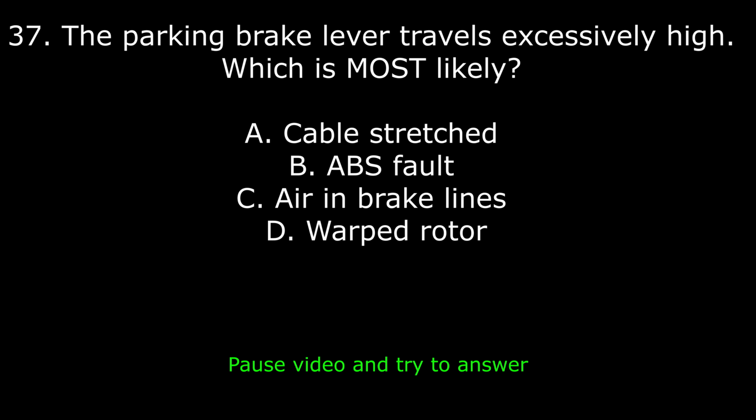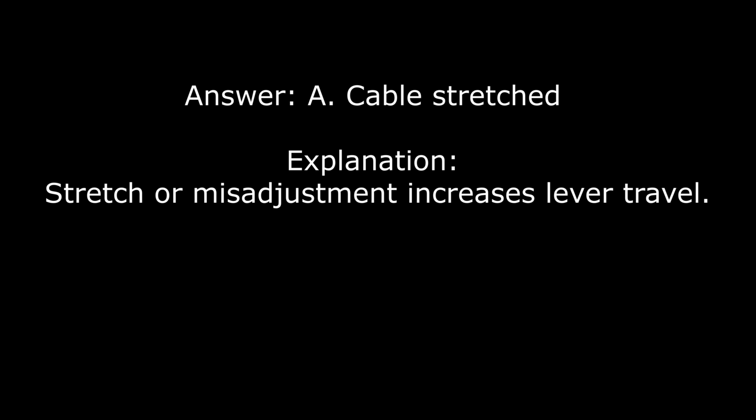37. The parking brake lever travels excessively high. Which is most likely? A. Cable stretched. B. ABS fault. C. Air in brake lines. D. Warped rotor. Answer is A. Cable stretched. Explanation: stretch or misadjustment increases lever travel.